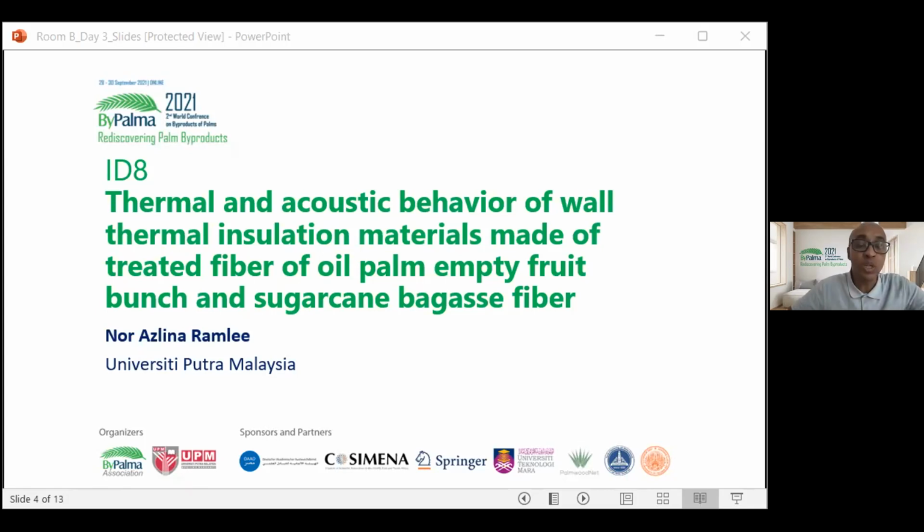I have just a quick question about the control of the density. You vary the density of your produced material because it generates the porosity for the acoustic insulation. For this project, I also did a characterization for the density, void content, tensile, mechanical and physical aspects.